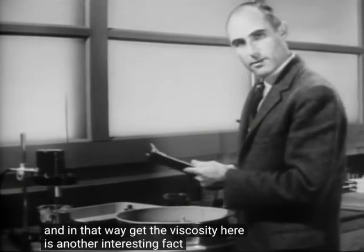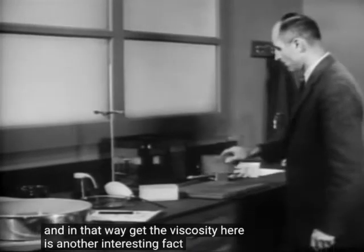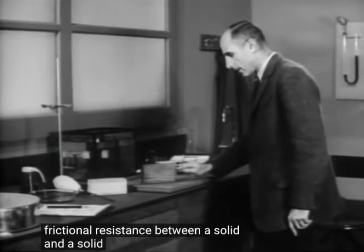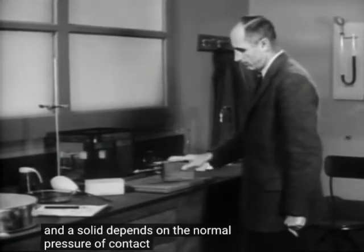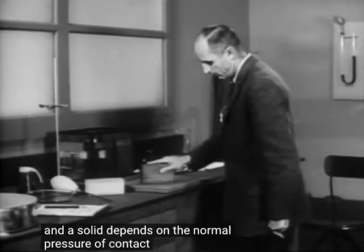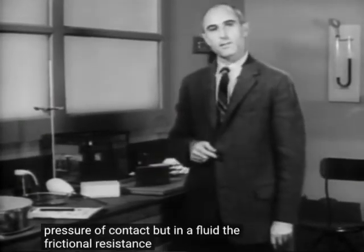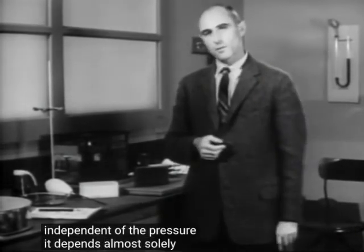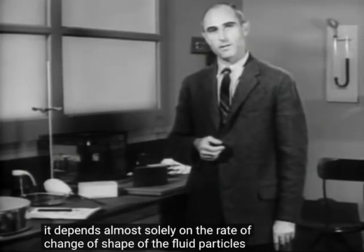Here is another interesting fact. The frictional resistance between a solid and a solid depends on the normal pressure of contact. But in a fluid, the frictional resistance is almost totally independent of the pressure. It depends almost solely on the rate of change of shape of the fluid particles.